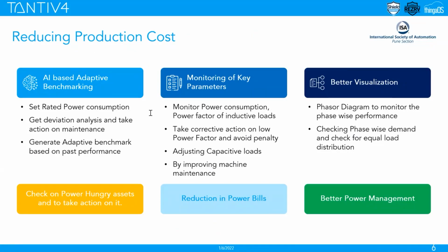Of course, controlling the bill is a priority, as one must avoid the penalties due to the power factor and maximum demand, but also gain the incentives in controlling the power factor. It means not only do you have to stop the penalties or the higher bill due to a low power factor, but you also get an incentive when you improve the power factor beyond a certain value. So one can save up to 7% in utility bills by taking benefit of these incentives.